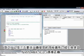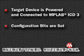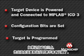To recap, remember these three key points. Make sure your target device is powered and connected properly to MPLAB ICD3. Make sure your configuration bits are set properly, especially the oscillator. And make sure your target is programmed. If you remember these three points, you should have no problem getting up and running in no time.